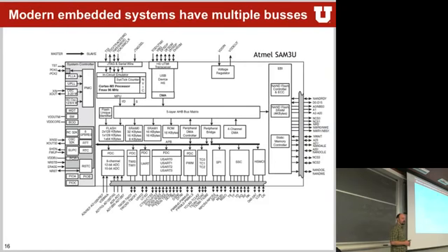If you look at a modern microcontroller, there are a lot of different bus systems out there. Oftentimes, the legacy buses that get talked about in embedded systems courses are the ones here on the side, which are external memory interfaces, so how you hook up to NAND flashes and SDRAMs. Down here, we have a lot of different serial and parallel buses to talk to, for example, SD cards, SPI buses, I2C, other serial buses, parallel buses. These are all external buses that usually go off-chip.